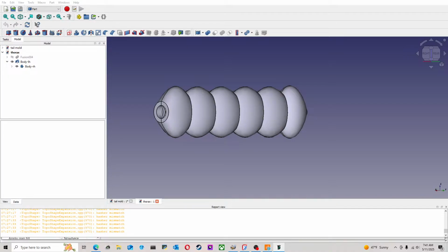Strength, we'll do 7 walls. Top shell, bottom shell thickness, 3 and 3. Support enabled tree. PLA. Slice plate. Two hours, 40 minutes, print, upload and print.